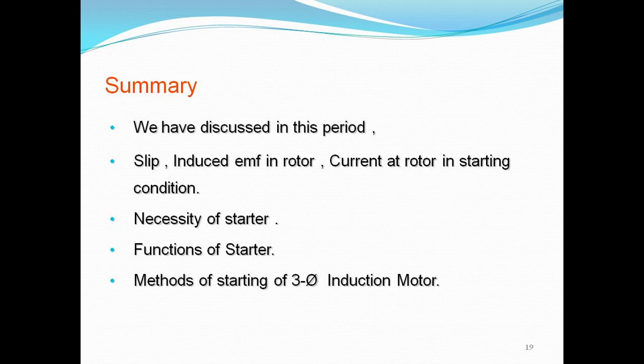As the motor picks up speed, we can gradually reduce the starting resistance, or we can cut it. When the motor reaches its normal speed, then put the handle in run position by cutting the entire resistance from the rotor circuit, and the slip ring terminals are short circuited.